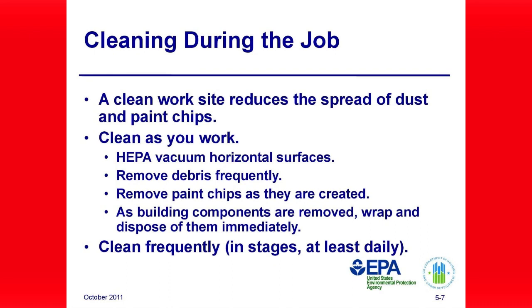How often should the cleaning during the job take place? The goal is to keep the dust and debris under control, not to maintain a completely spotless site at all times. Every job is different, so clean when it makes sense to, without hindering progress. Remove large amounts of dust, paint chips, and debris frequently and at least daily.